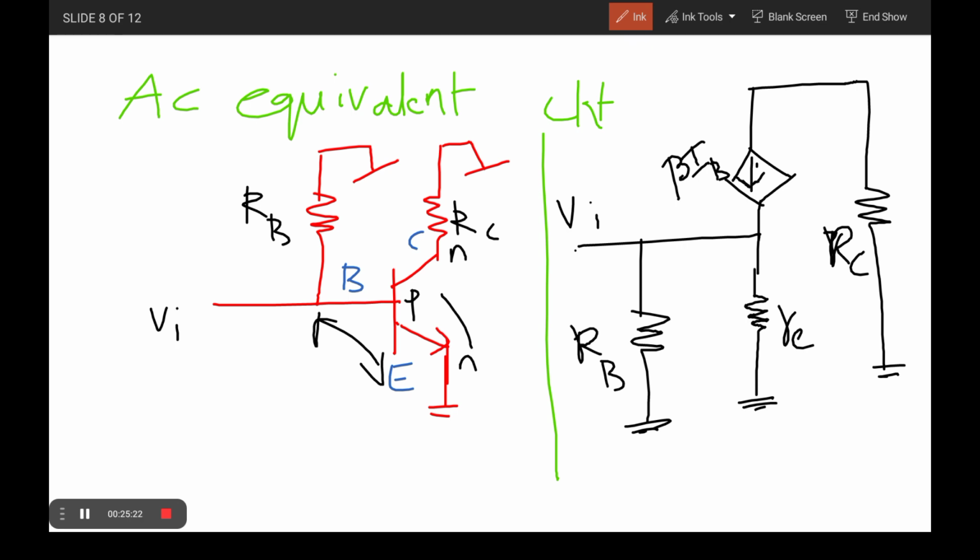Why? Because if the transistor is in the linear region, or maybe the forward active region, it behaves as a current source. At the same time, if the transistor is operating at the Q point, or the operating condition, it behaves with a linear nature. In the linear region, whatever input you apply to the transistor, it passes through directly without any degradation.